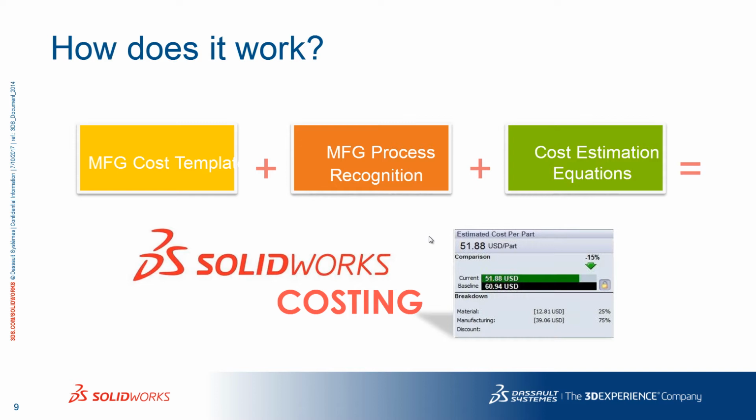After that, you have to build some equations and some assumptions. For example, how many hours are you working per week? And what could be the average cost of labor in the workshop? So there will be some assumptions here, and we will talk about some of these assumptions in a minute. And then you have to build your cost templates according to that. You can use one of the cost templates that's inside SOLIDWORKS. However, I'm not recommending that, because the cost template inside SOLIDWORKS is just a sample template. So you have to build your own and change all of the data inside the cost template that comes by default in SOLIDWORKS.